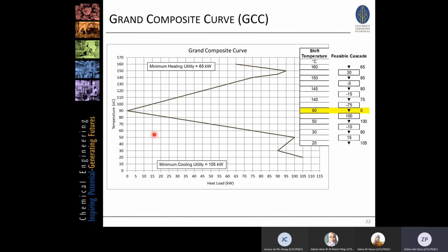So are we going to dump all of this to the cooling tower? We don't know. Because this is 90 degrees C, in some areas they can recover this heat to make hot water. They can make hot water from 60 degrees C to 90 degrees C, for example, so we can touch the whole line over here. 60 degrees C is somewhere there. So that amounts to 73 kilowatts. They can reuse it to make hot water, which is then used for, I don't know, office uses or whatnot.